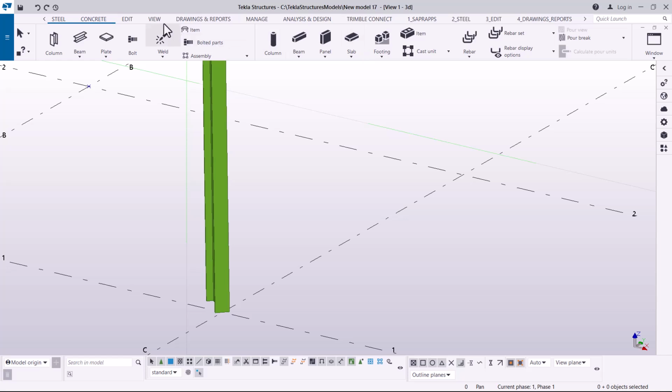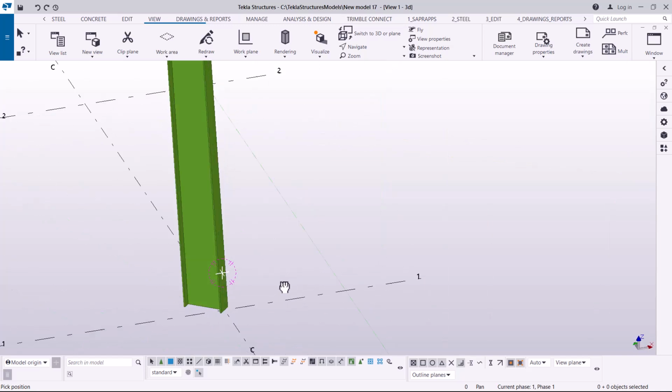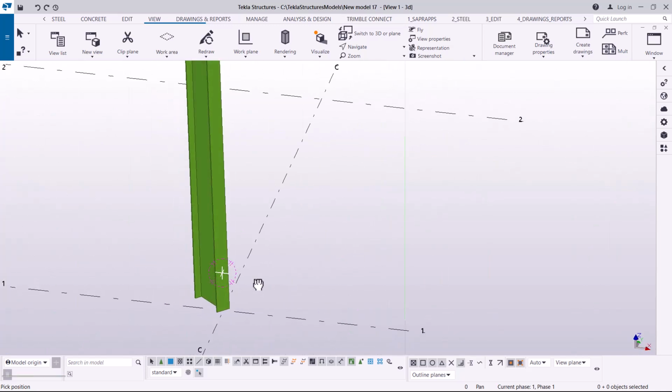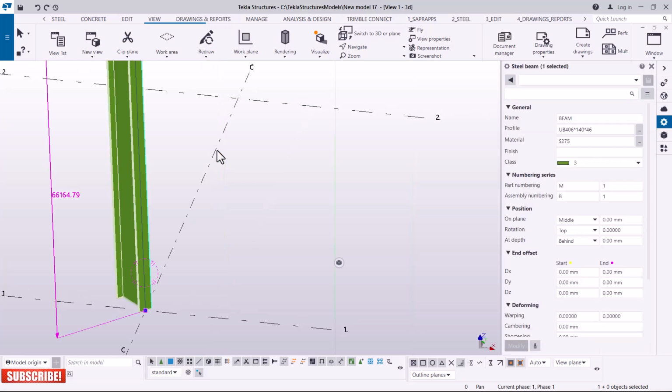In here you can see the default profile is a beam, and a beam is a very strange member to use as the leg of our telecommunication tower. So we have to modify this to take an L profile. I'm going to double click on this member by left clicking. This will bring in an editor dialog box of a beam profile like you see here. Under general, you can define or key in leg, or just leave it as it is, or key in whichever name you prefer.